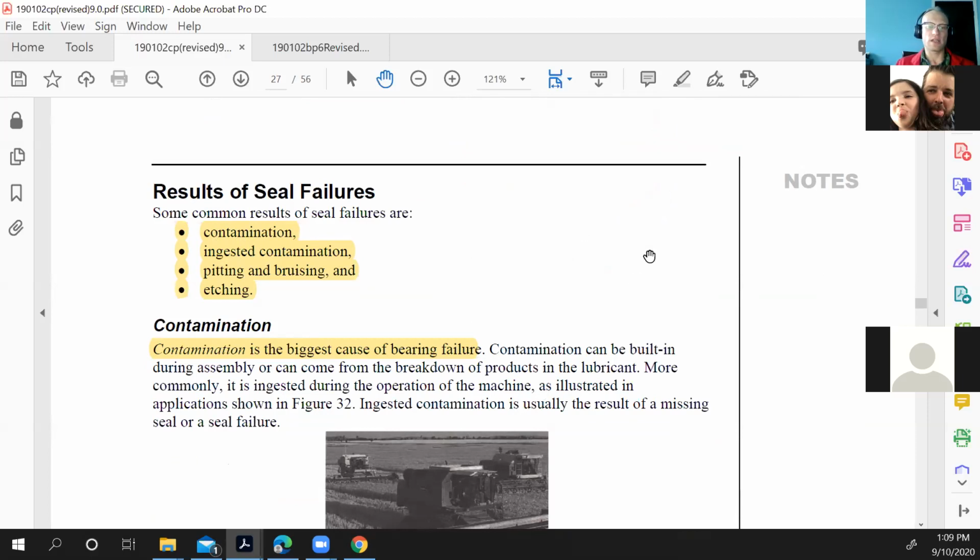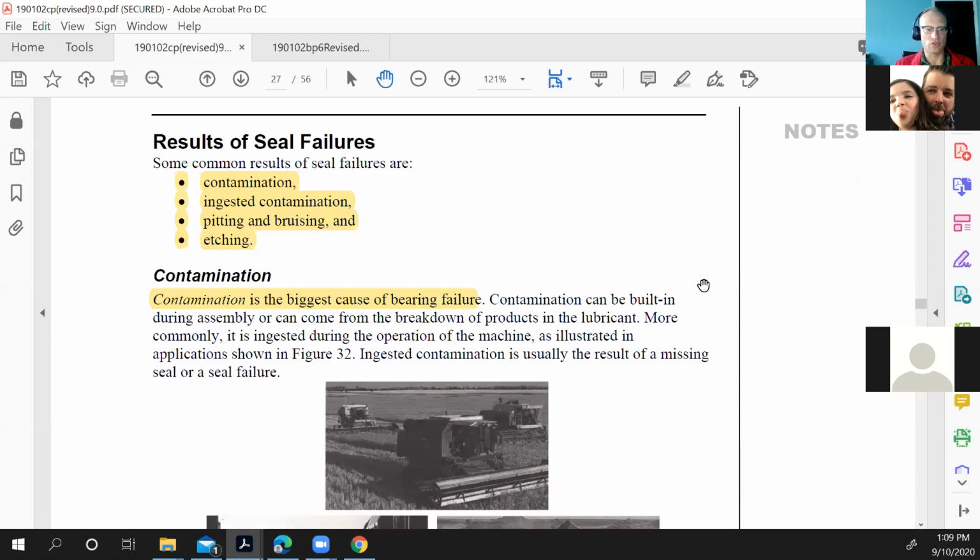The other source of contamination comes from us. So when we're installing in a very, very dirty bay and we're not cleaning bearings properly, it can destroy them. It only takes about a tablespoon of contamination to run through like a transmission, and it'll destroy all the bearings inside of it, okay? As well as a bunch of gears, and it's very, very bad.